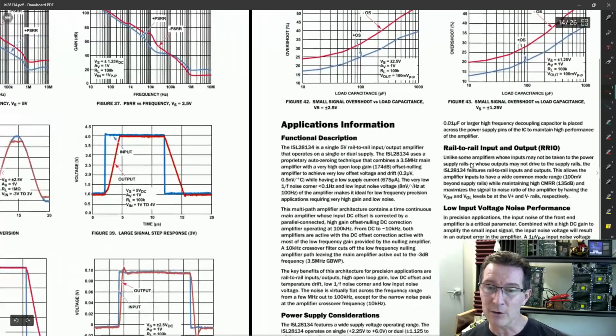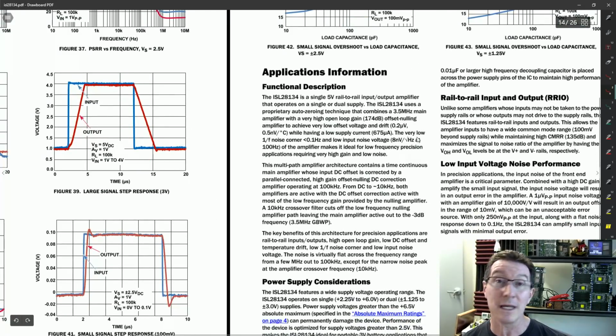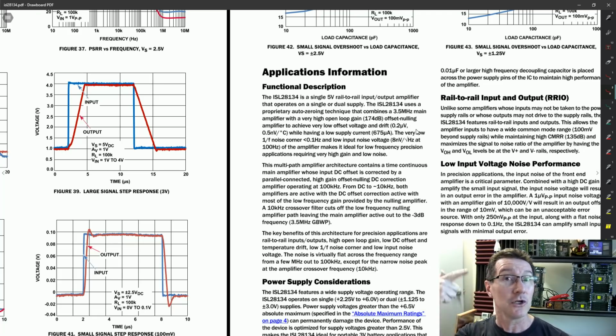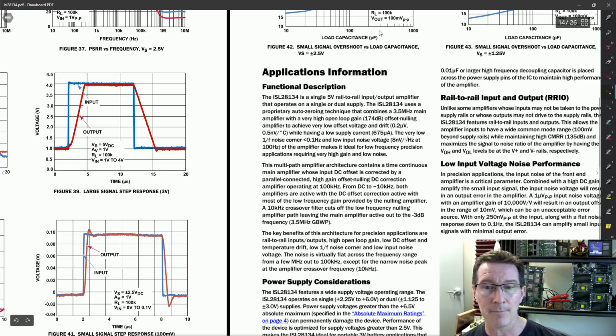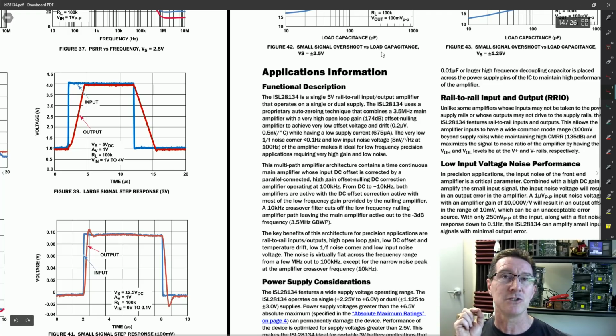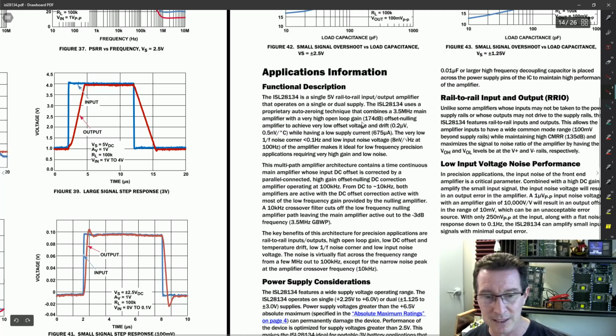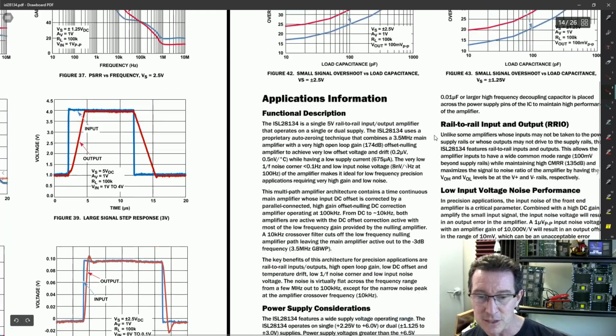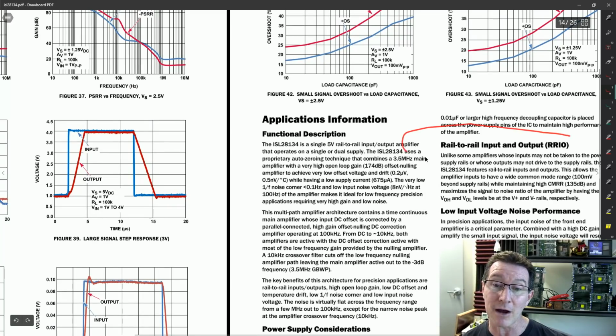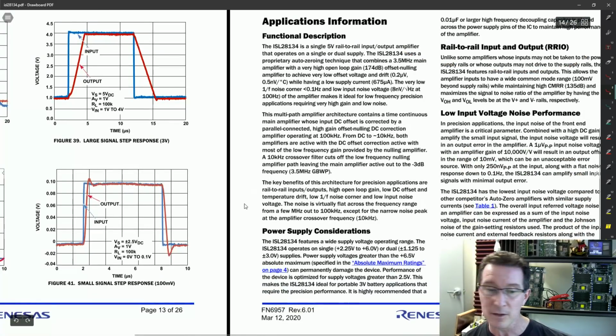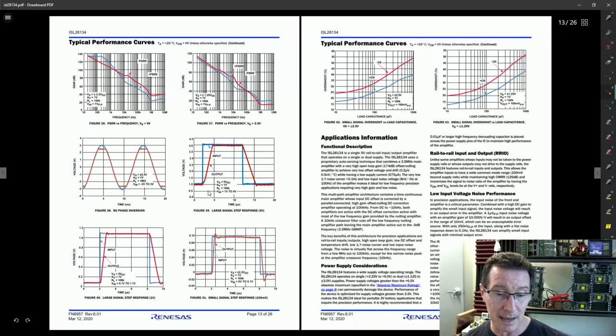So it's rail-to-rail input, of course. We don't need a rail-to-rail input because we're measuring just from, unless you had a single supply and you wanted to measure right to ground. But rail-to-rail input is not necessarily ground sensing, so just be aware, they can be different things. But anyway, the rail-to-rail input and output, that's quite nice. So yeah, that's not a bad part.